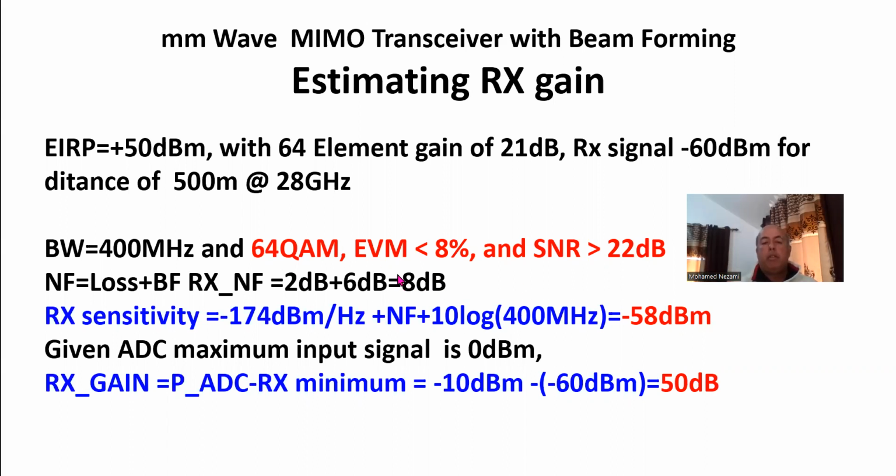And that is usually how it's implemented. The technology doesn't allow you to really get down to noise figures below this much, because you have splitters and phase shifters and again variable gain attenuators. So you end up with this kind of number for the noise figure.